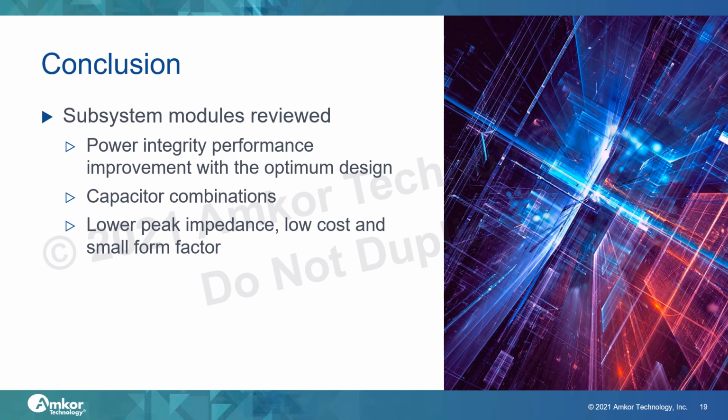Optimized capacitor configuration met not only target peak impedance, but it also reduced cost and form factor size. These analytical results can be used in design guidelines, which can be estimated in the pre-manufacturing process of subsystem module packages.